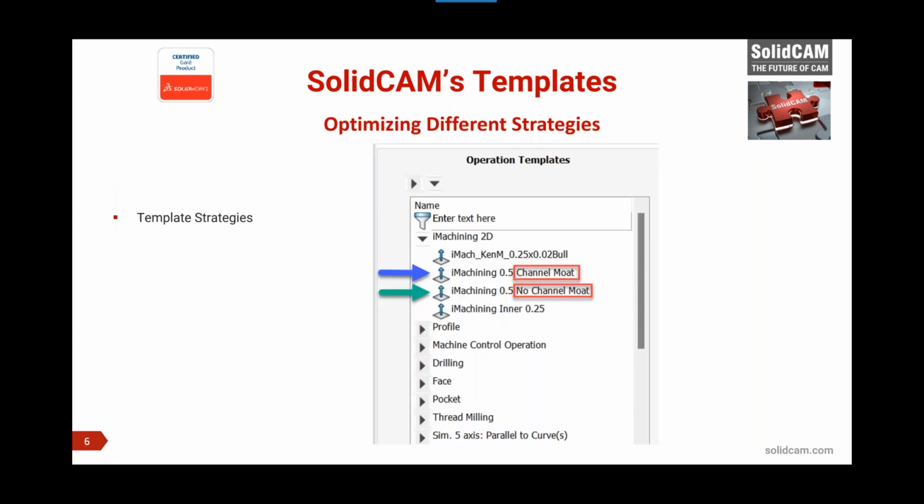Now, I noticed you did it actually on 2 surfaces. I did actually, and I was just about to talk about that. You can drag a template directly to a face and pick it, or what I did in this case was I used the control key. Now, holding the control key while dragging it to the first face and then continuing to hold that key as you pick the additional faces will allow you to assign that template to multiple face selections for the feature recognition to work in each of those areas. So the performance improvement over other systems in doing this is very, very exceptional.